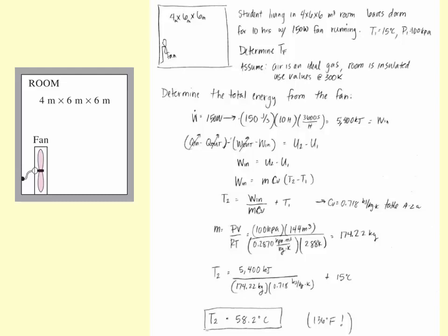If we really wanted to be thorough about this problem, we can say, okay, using that specific heat, I've solved and I found 58.2 degrees as my second value, or 331.2 Kelvin. So then you go back to the table and you find the average specific heat. Using that new specific heat, you redo the problem again until you get the final temperature, which would be maybe slightly different.